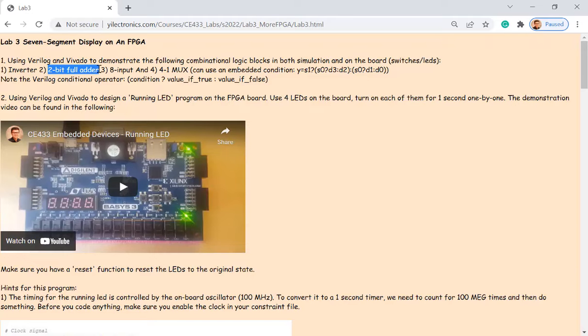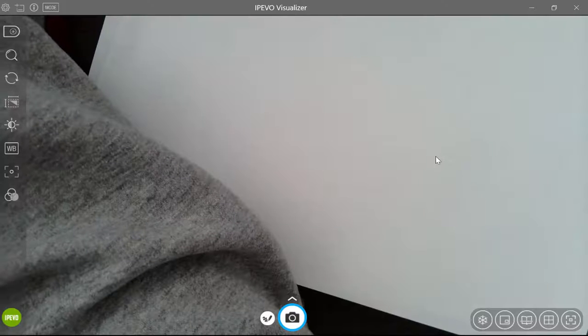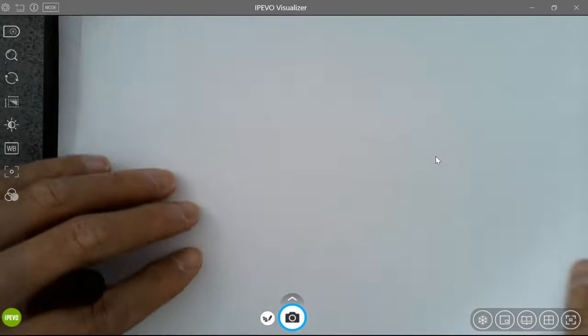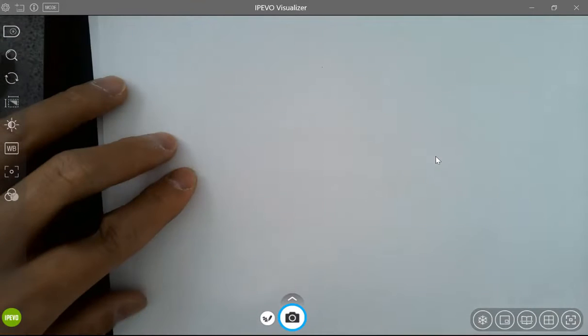2-bit adder. When I was looking at examples from 2 years ago, students submitted a 1-bit adder instead of 2-bit. The 1-bit FA adds 2 bits, so that's why it's confusing. They're thinking, all right, a 1-bit FA is a 2-bit FA. Actually, it's not.